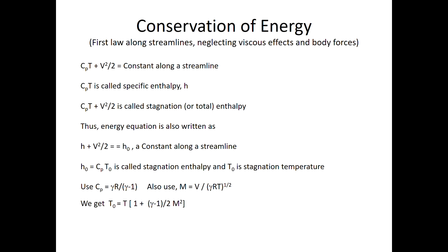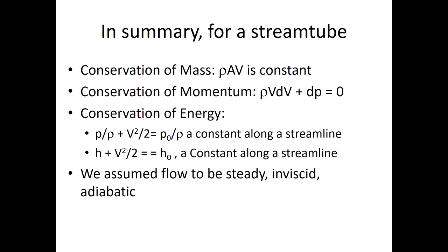So in compressible flow, we will use this equation rather than the Bernoulli equation. How about the second law of thermodynamics? Okay, this is the summary. Conservation of mass for a stream tube, conservation of momentum, conservation of energy, and the assumptions are steady flow, inviscid flow, adiabatic flow, no body forces.